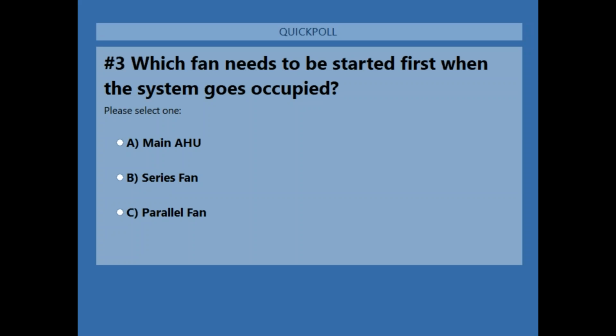I should also mention that sometimes these VAV boxes are ordered with filters on the plenum inlet, which is not a bad idea, but those filters are only for construction time. You put them on there to keep all the drywall dust out of your VAV boxes, because many of these guys in the building are going to want to run the heat to help dry drywall adhesive and paint and stuff like that before the building's occupied, and I don't want all that drywall dust on my fan or my electric heat or anything like that, or my hot water coil.